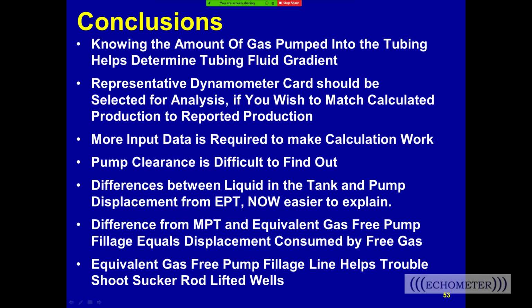Okay. Jun Shu is asking, Lynn, how to determine the tubing gradient more accurately when gas is present, when not knowing how much gas is entering the pump? Yeah, well, that's what I thought. I thought when we did this that we put the multi-phase flow method in the software, and we used the gas up the tubing to calculate the gradient based on multi-phase flow, and I thought that would be really accurate. We still have some work on that, but it works really well for really high oil cut wells now, and we've gotten a lot of good matches on that. There may be a bug we just need to look at some more, but it doesn't do very well yet for water. But we are doing that.